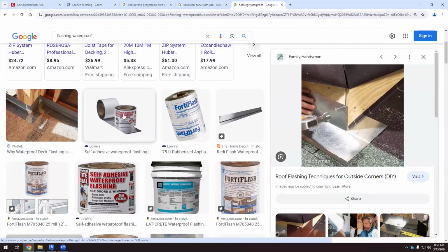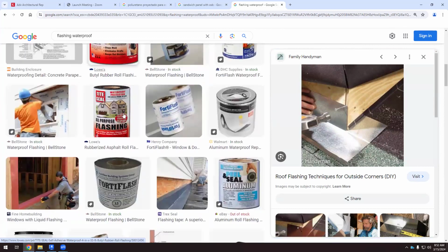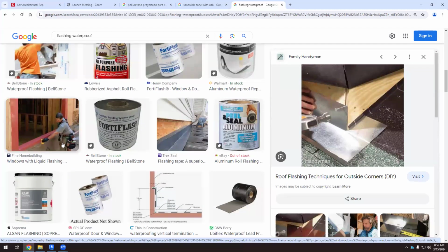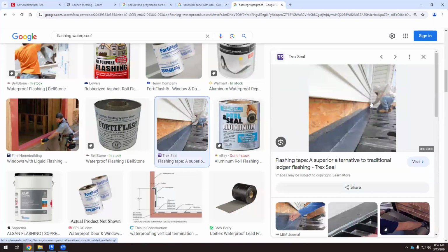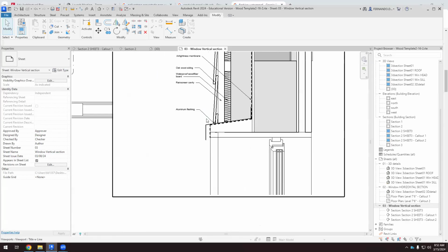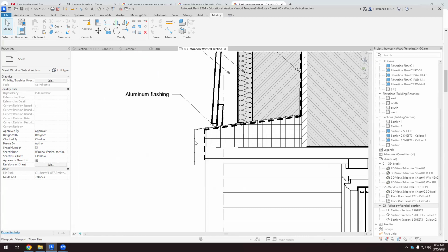We have a roll here, well, maybe it works. What is this? This is a roof, and this is a wall that goes beyond the roof. So this connection between the wall and the roof, we have to protect it with this flashing. Or when we have a window, every time we have an opening, we have to use this kind of flashing to get rid of water.